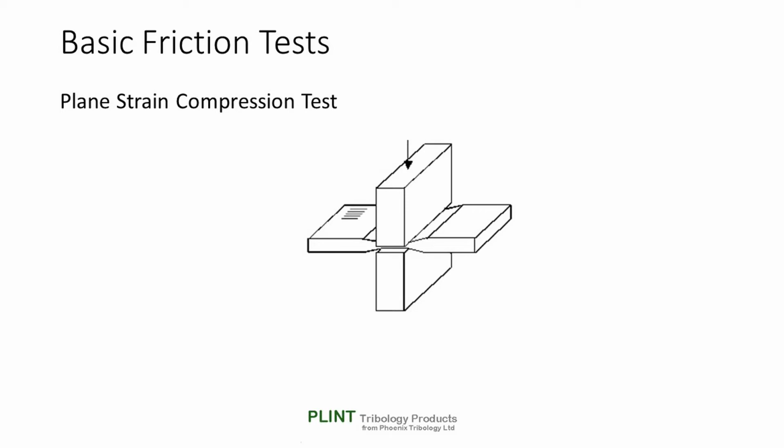The plane strain compression test is used to estimate values of friction coefficient under boundary lubrication in rolling processes and to investigate the generation of fresh material and deformation and cracking of oxide films. Measurements of friction correlate with build-up of transfer layers.